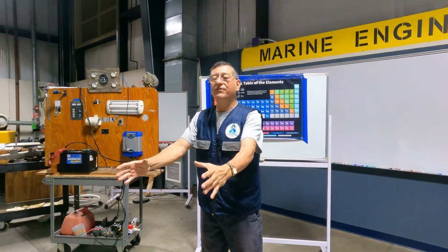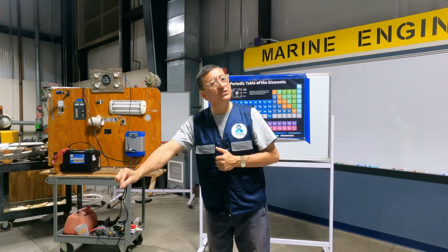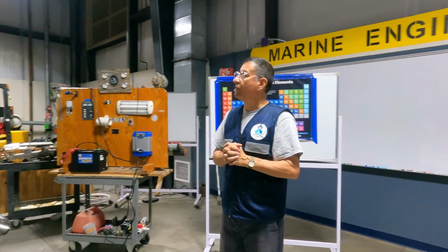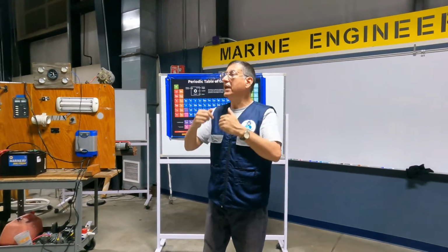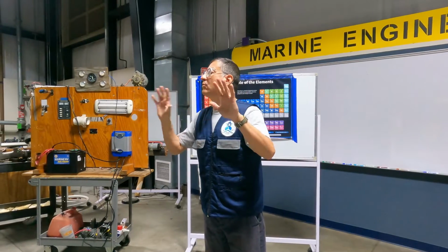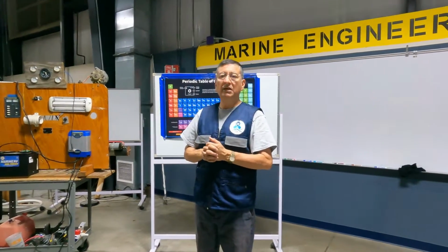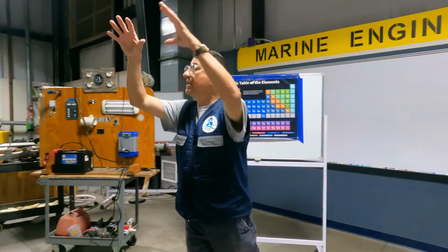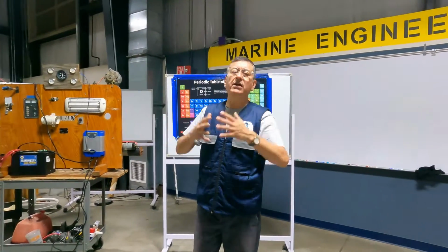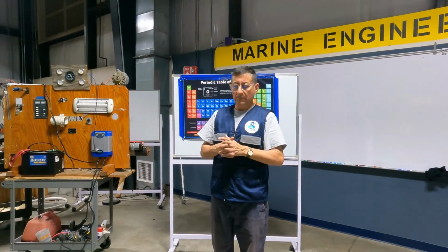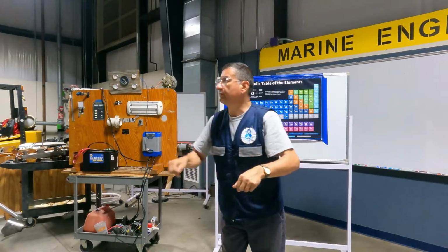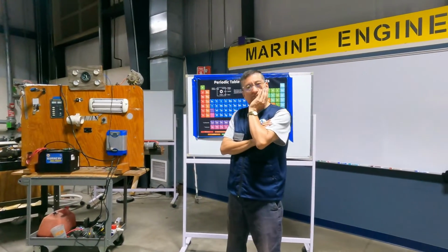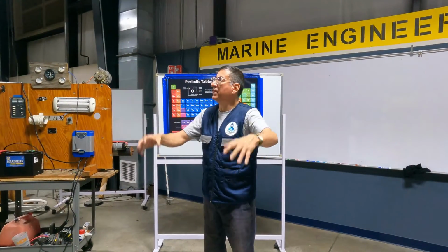We are going to continue with the refrigerator. The ground cable is not connected, and a lot of energy is stored on the case of the equipment. Look at this. Additionally, this refrigerator is not marine grade equipment. It's a Home Depot refrigerator in your boat. The housing of the refrigerator is regular steel. The brackets in the bottom are aluminum, and the rivets and screws are copper. How many dissimilar metals are over there?